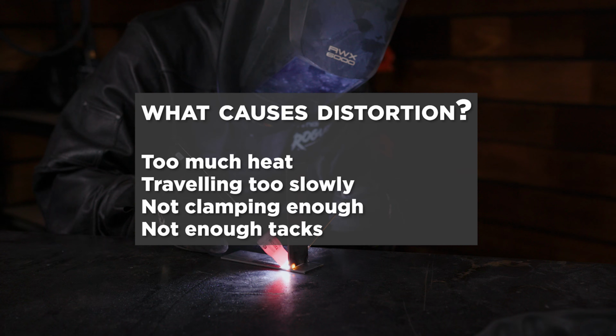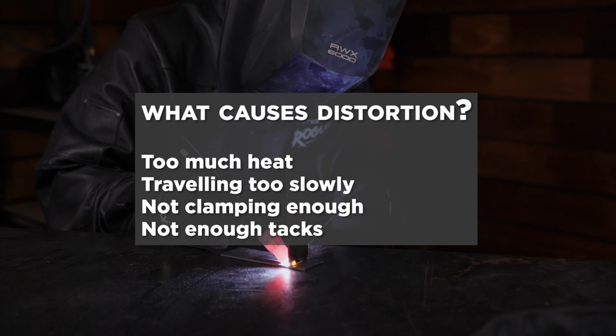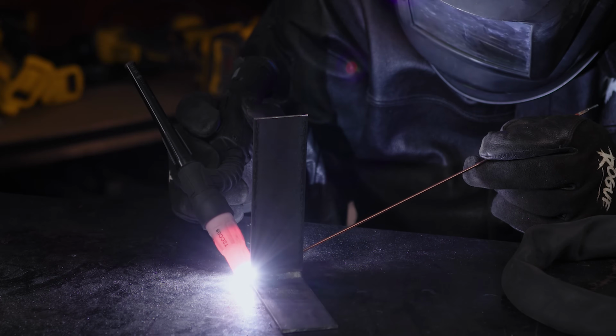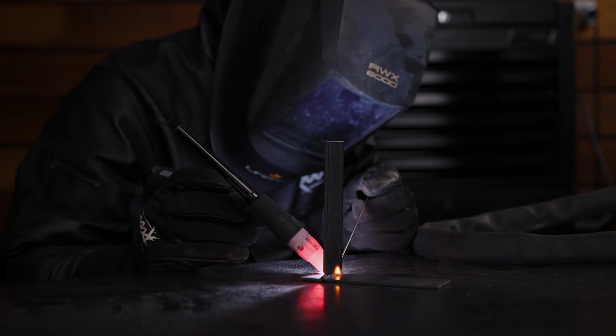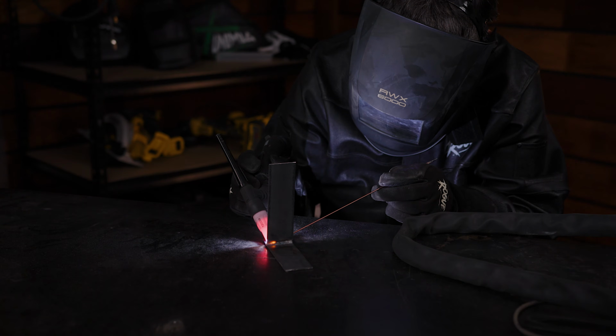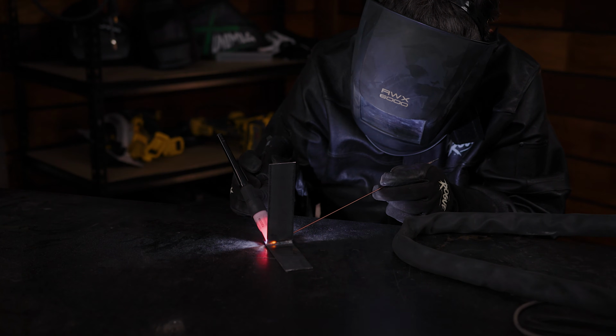Too much heat. Traveling too slowly, not clamping enough, or not enough tacks. How can you fix or prevent it? Where possible, do short welds or stagger welds. Increase your travel speed, but up your amps so the puddle still forms, so less heat sinks into the parent metal. If you're working on thin sheet metal, spot welds or staggered welds can spread the heat.